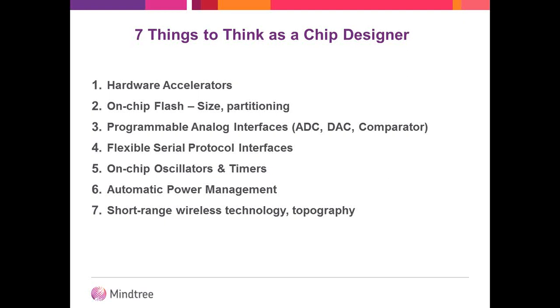The third thing is about analog interfaces. Of course, ADCs, DACs, and comparators are very much required, but you may want to look at making them programmable, because today you don't know what kind of user interfaces people will use your chip for. So you better have it be very programmable, where users can program your analog interface to match the sensing that you are trying to do with this chip.